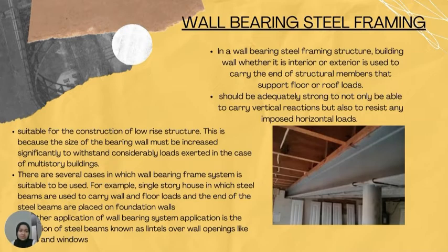There are several cases in which wall-bearing frame systems is suitable to be used. For example, single-story house in which steel beams are used to carry wall and floor loads and the end of the steel beams are placed on foundation walls as shown in figure on the right.